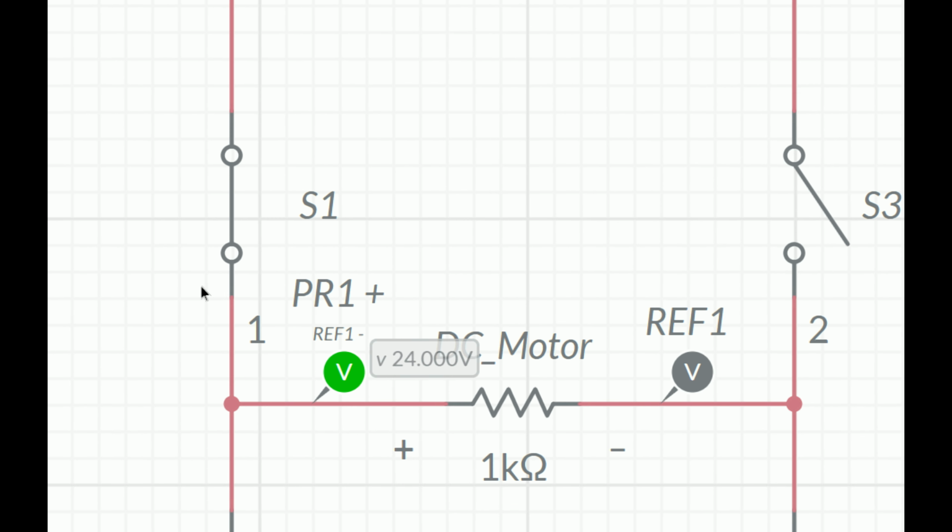So that way the power goes here and this terminal has become positive. Now to make this terminal negative, to make the motor move in one direction, we keep this switch open, because if this switch is open and we close this, it will get shorted. So that is the beauty of the H bridge. This switch is open. Only if this and this switch are closed, then your motor moves in one direction.